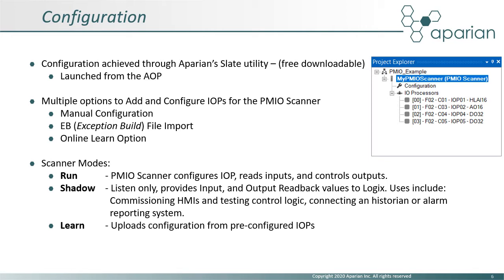Before looking at these configuration options in more detail, let's briefly describe the PMIO scanner operating modes. Run mode is where the PMIO scanner configures and controls the IOPs and is engaged after the Honeywell process managers have been removed from the system.